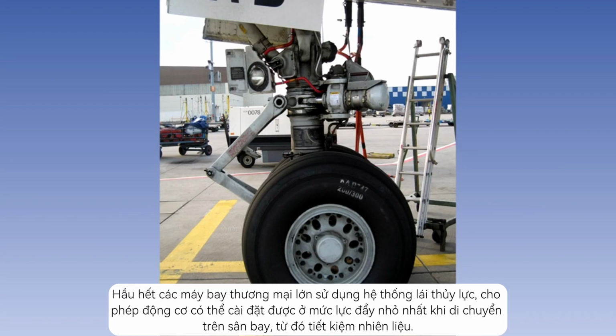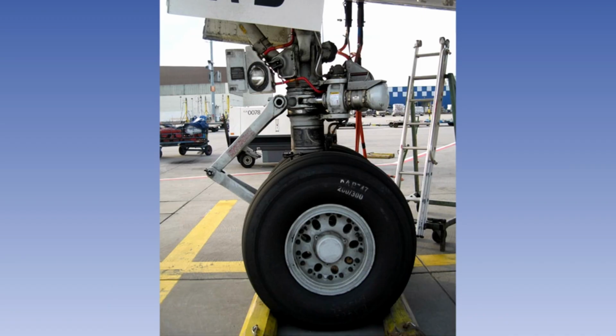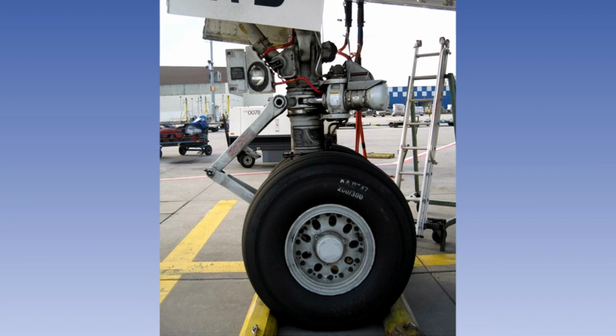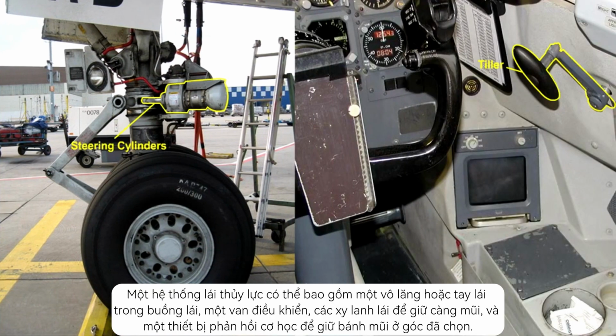Most large commercial aircraft use hydraulically powered steering systems, allowing the engines to be set at the minimum thrust for taxiing, thereby saving fuel. This method of steering is more accurate. It also reduces tire and brake wear and noise pollution. A hydraulically powered system may include a cockpit steering wheel or tiller, a control valve, steering cylinders to hold the nose gear, and a mechanical feedback device to hold the nose wheel at the selected angle.